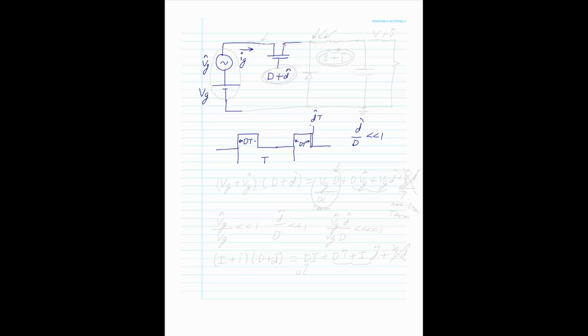And this is the AC signal. It's small signal analysis. You do that with everything. You do that with amplifiers. When you bias a Class A amplifier with your DC and get your midpoint, and then you put a small signal AC on it with a gain on the output, you're doing the same thing here.